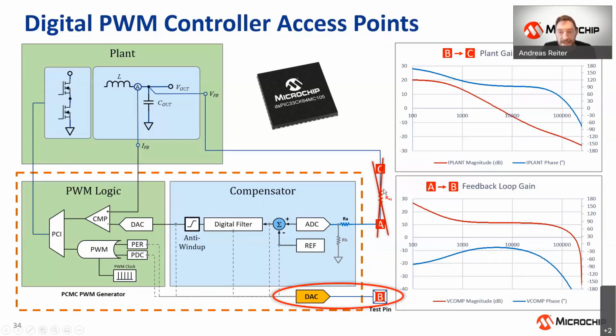So the way we're doing this is we're just moving the injection point. Now we still need to wire up our reference and sense probes. And the sense probe is the one that is most critical, because this is what eventually gives us our measurement result. And for that connection point, we're utilizing this internal DAC.